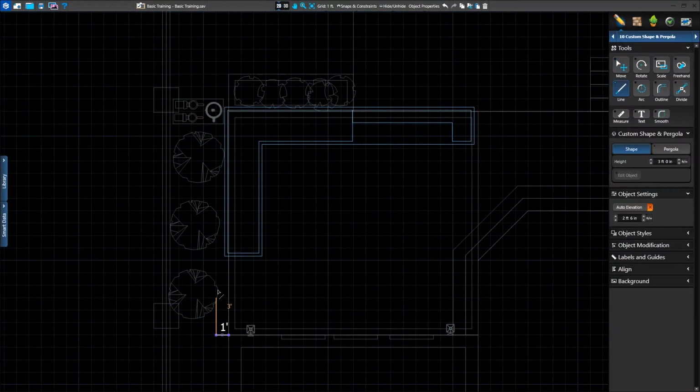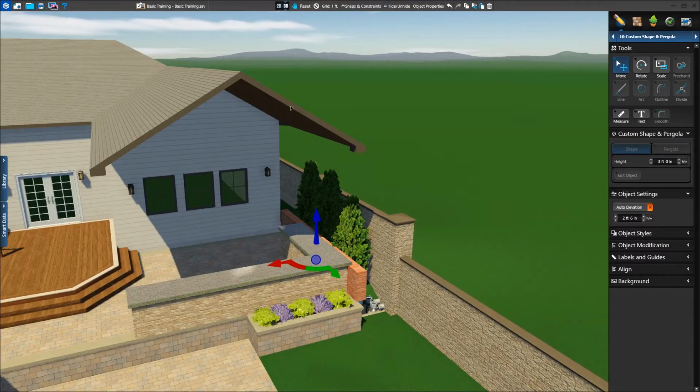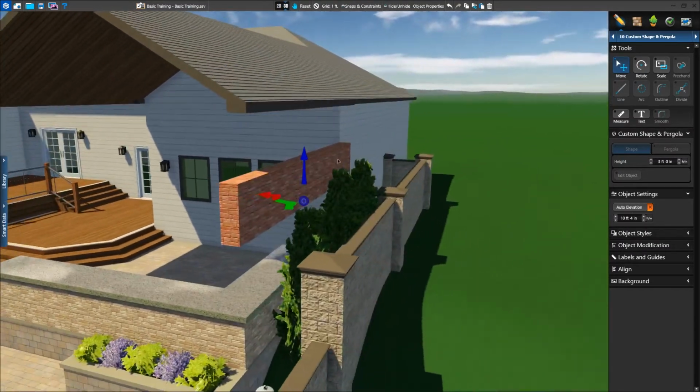Using the Line tool, we'll follow the edge of our house shape, but since we want our beam to extend past our roof, we'll continue drawing past the edge. We'll then draw 1 foot to the right, then back down to match our original line and complete our shape. When we return to 3D, we see a shape that matches the settings of the last kitchen base we created.